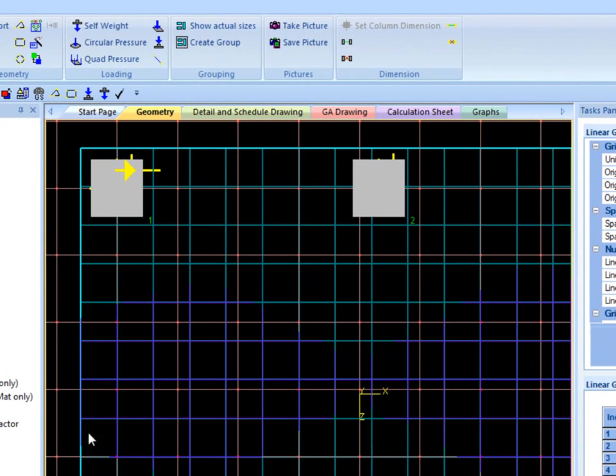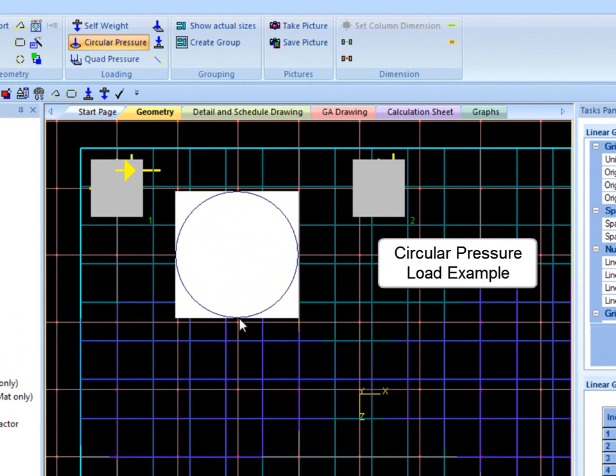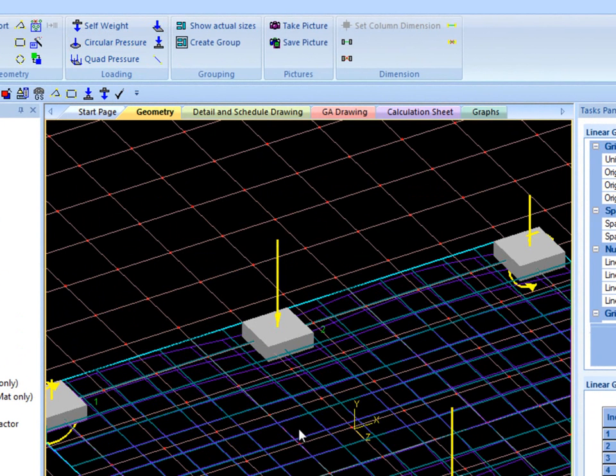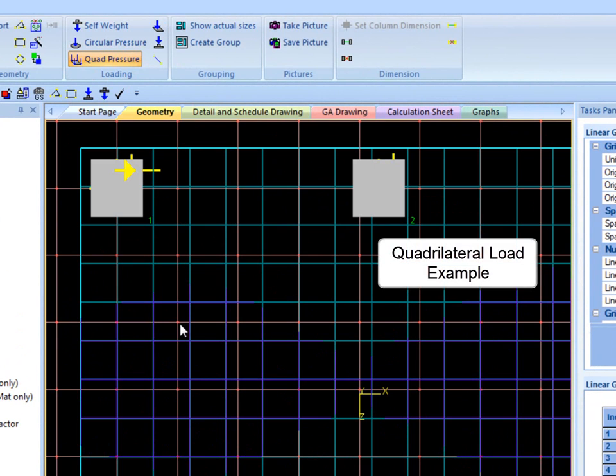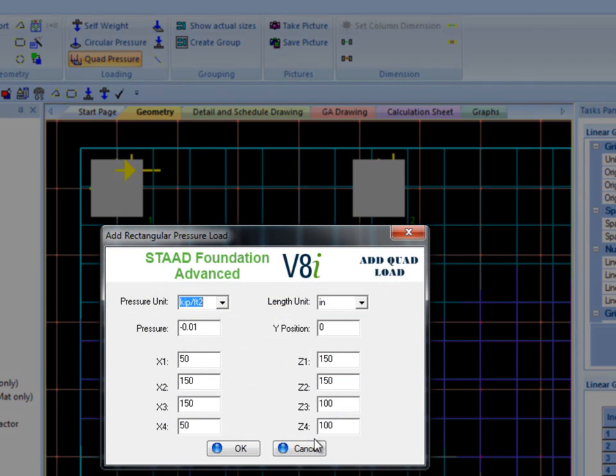It's important to note that when creating mat-specific foundation loads with the icons under the Tools menu, both the points where you initially click and let go must be a grid node. Then you may enter the required information in the pop-up wizard. Information generated by node selection can still be edited through this wizard.